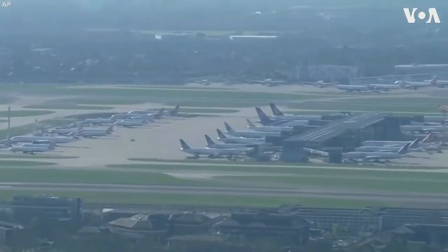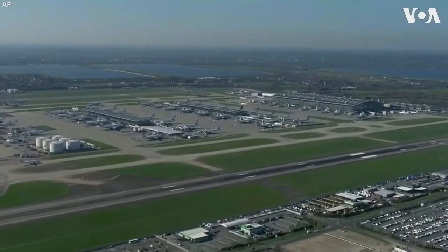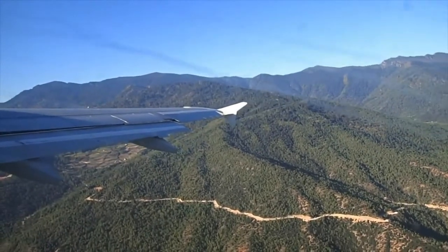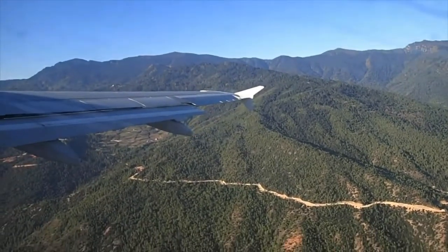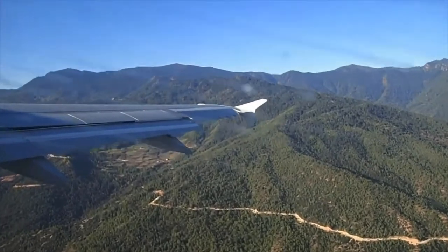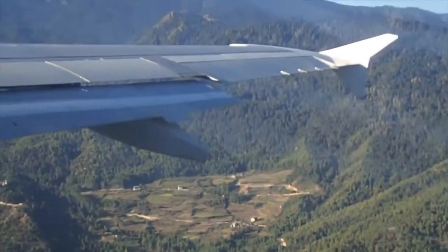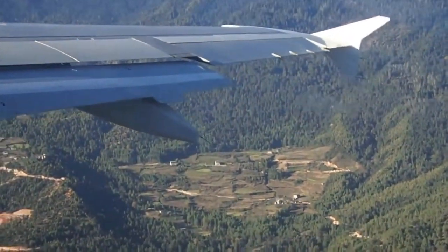Have you heard the transmission of the air traffic controller? He's mentioning altimeter, isn't it? Okay, we'll hear it once again. Temperature 20, dew point 19, altimeter 3005. So, QNH is the barometric altimeter setting that causes an altimeter to read airfield elevation.